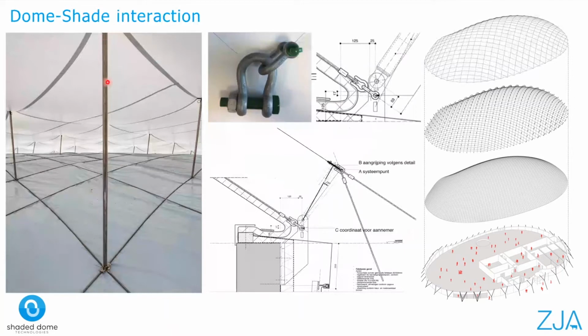Next come the struts or the spacers that form the link between the dome and the shade above. The shade consists of steel cables running along the edge, as you can see here. This one, yeah. The edge of the shade is further tensioned by anchoring it to the ground by using suspension cables. The shade is also connected to the wall via a bracket. This bracket detail is in the middle of your screen. It holds the cable, which you see here, with these harps and the struts with a hinge connection that is further bolted to the concrete wall.